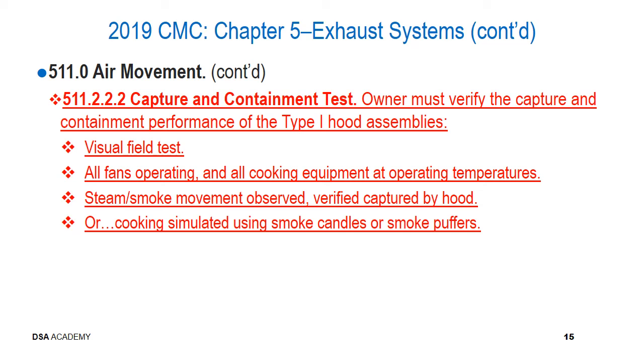And this includes a visual field test, and this visual field test is conducted with all fans operating and all cooking equipment at their operating temperatures. The steam or smoke that is generated, the movement of the steam and the smoke is going to be observed, and it's going to be verified being captured by the hood itself.